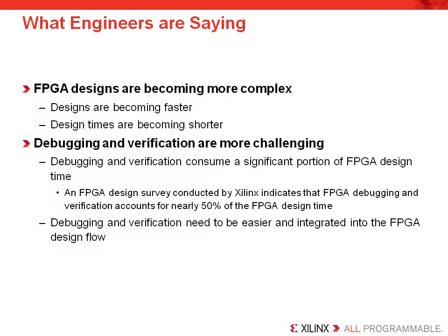To help improve design time, Xilinx recommends the use of its ChipScope Pro software. This enables die-level testing of a design by applying stimulus to internal nodes of a design and retrieving the resulting signals using ChipScope cores built with FPGA resources. To do in-circuit verification with ChipScope, you will apply stimulus to many nodes in the FPGA and store the generated signals using FPGA block RAM and other logic resources. The generated results can then be displayed with a ChipScope Pro logic analyzer. This allows you to quickly verify the operation of many nodes and verify the operation of your device in circuit.